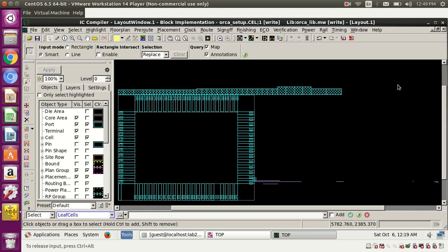We have two cells. This A pin should connect to this Z pin. Here the M1 width is 10 microns, but the M2 width is 1 micron and the M3 width is 0.5 microns. They are connected in M3. So from M1 they went to M2, and then they are connected in M3. Now what will the timing be?